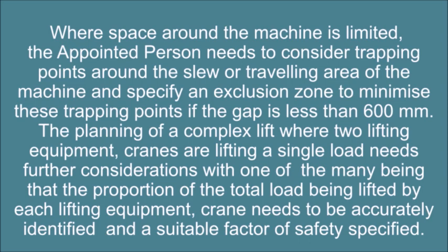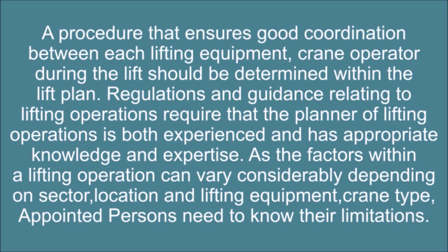The planning of a complex lift where two lifting equipment, cranes are lifting a single load needs further considerations, with one of the many being that the proportion of the total load being lifted by each lifting equipment crane needs to be accurately identified and a suitable factor of safety specified. A procedure that ensures good coordination between each lifting equipment crane operator during the lift should be determined within the lift plan.